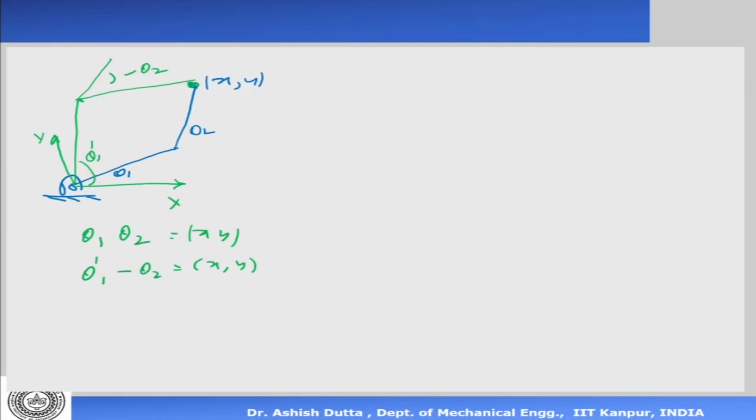And why is this happening? This is happening because the sine and cos have two terms. Okay, so this shows you that there are two solutions actually, and what we call multiple solutions. Okay, so if you have higher degrees of freedom, you will have more number of solutions. So because of this, we do not take the inverse there, because you will get a plus and a minus. Now the software, if you're writing a computer program, it will not be able to distinguish between minus and plus.